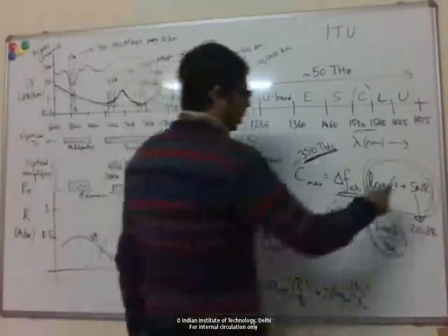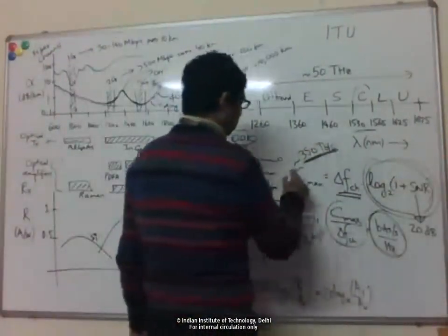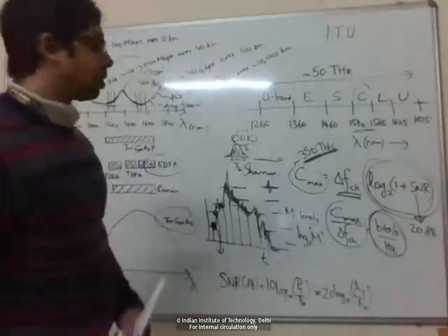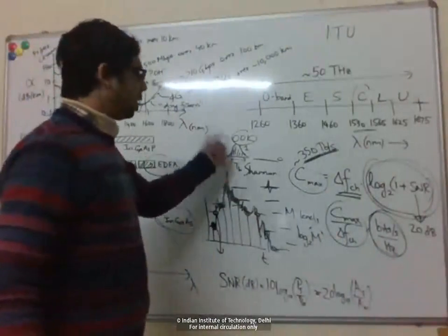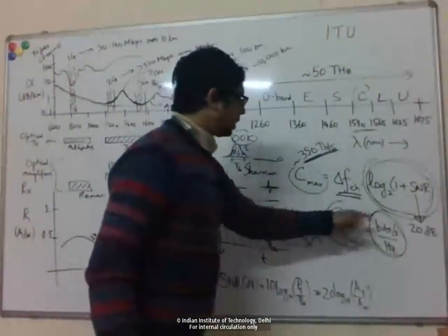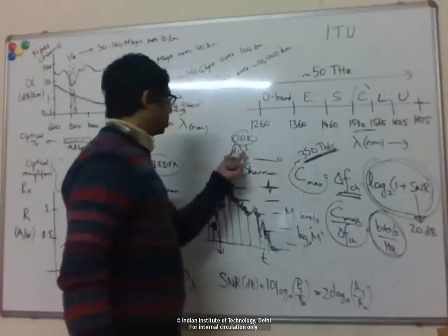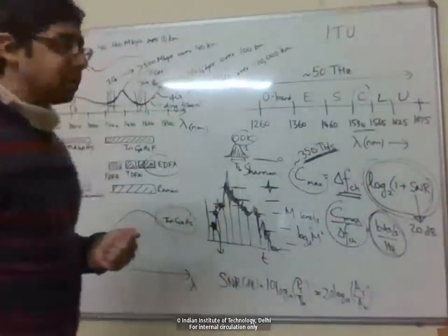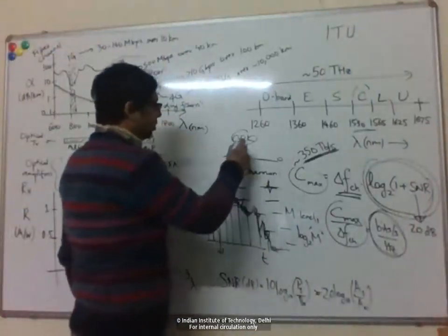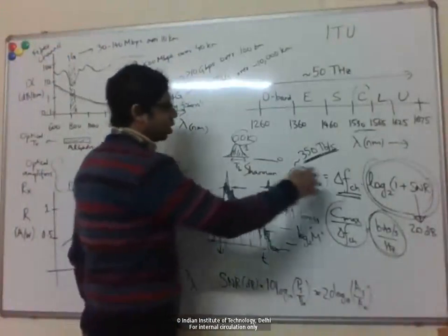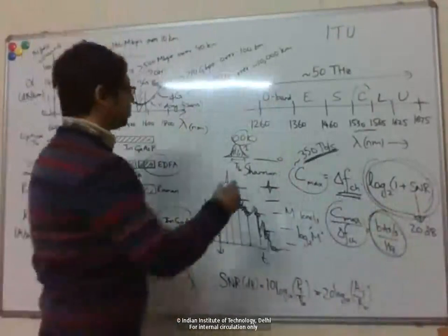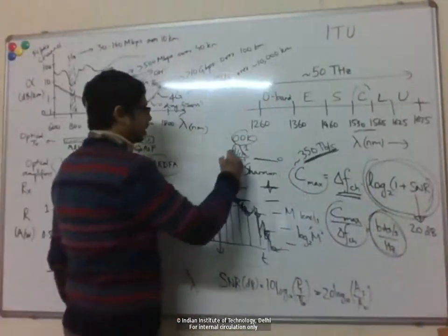Now, if you want to increase SNR and increase this channel capacity, you have to go to a different kind of modulation, because with this modulation, even if you increase SNR, you're not maximizing the spectral efficiency. You're still ending up at 1 bit per second per hertz. Another way to see it is that for this kind of communication system, an SNR of 1, anything more than 1, is enough. For 0, I'm not sending anything.